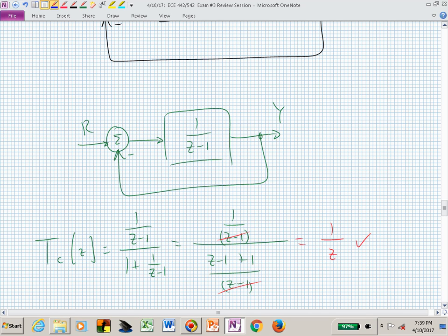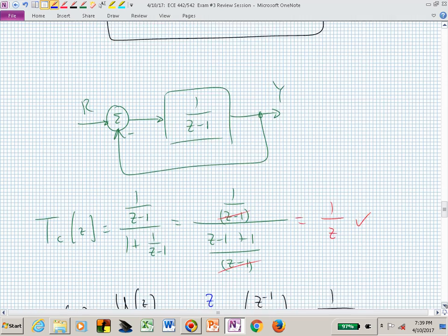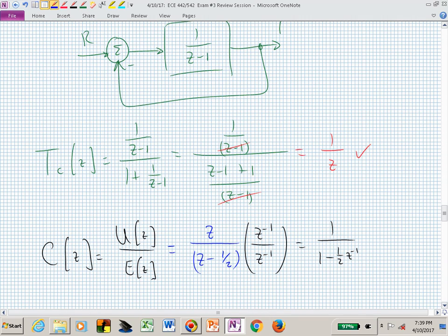And if we move back to earlier in the semester and somebody says, well, okay, you've designed a controller. Now maybe they say, can you build that in a computer? Can you realize this controller transfer function? We know what C of Z is. C of Z, we just computed to be Z over Z minus 1/2. And we can now find the difference equation relating the error signal in our block diagram to the input waveform U that drives our plant.